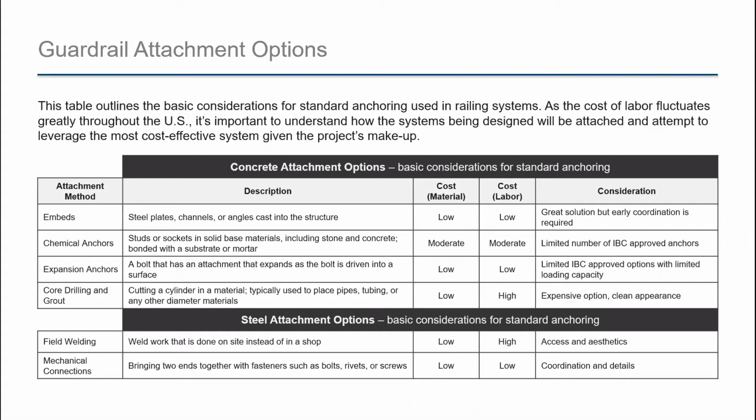A chain is only as strong as its weakest link, and if the connection to the structure is not possible, then the railing is really no good. You end up having to change the geometry, and it's probably affected negatively when you compare it to the original architectural concept. For example, you may have to greatly reduce post spacing, or base plates can become very large if you're attaching to a very thin slab. So you do want to look at this very closely in the early design process.